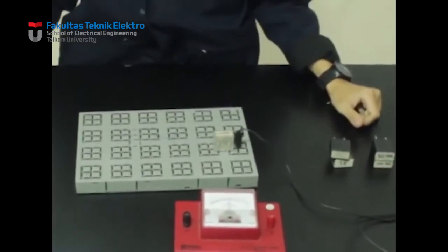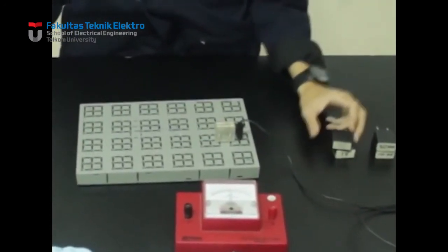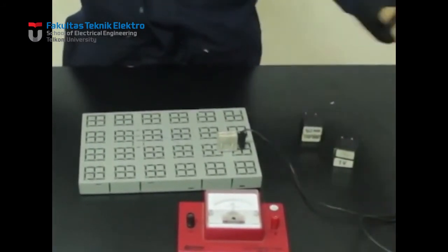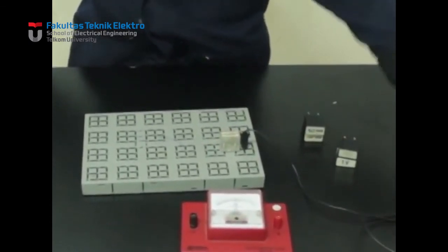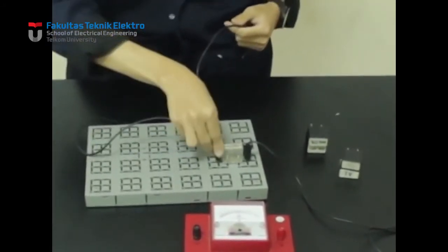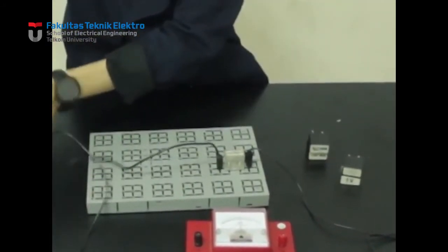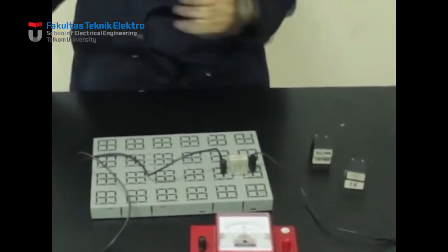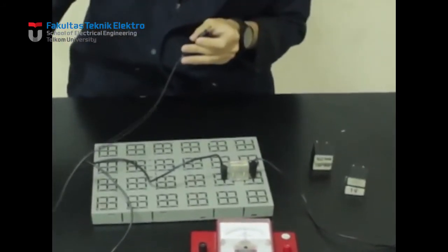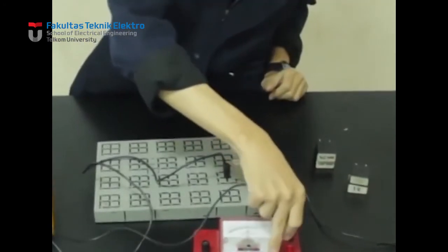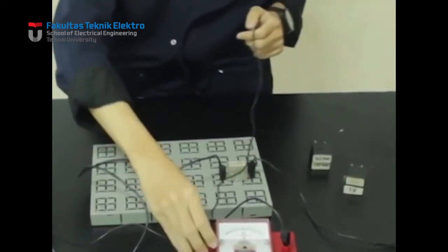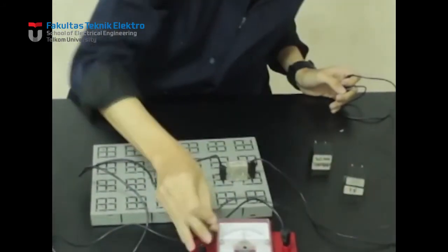For the second submodule, we will still use the same tools, but this time with the help of a shunt resistor. The first practicum step is to connect the power supply with a jumper to the resistor, then connected in series with a multimeter. After the multimeter, we proceed to the galvanometer and then return to the negative pole of the power supply.